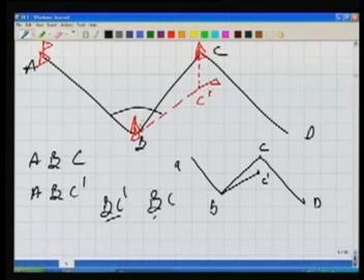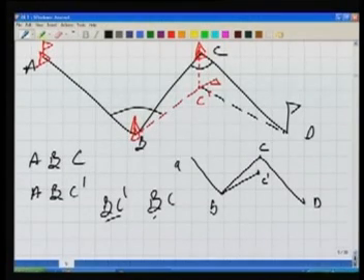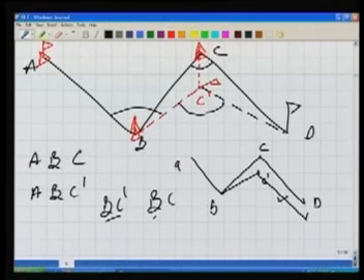So because of that, now we put our theodolite at point C and we measure the angle. There is no miscentering error, so we measure the angle BCD. Now what happens in the plot? In the plot we have plotted at B a wrong angle ABC dash. Now at C dash we form the angle BCD. So this BCD, if I draw it like this, is smaller than this angle. So an angle smaller than this will be plotted like this, and then I plot the length.